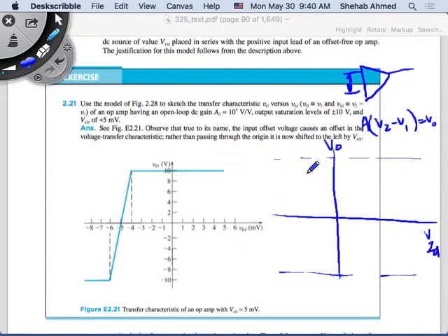And that's why, if the offset voltage exists and you put a short circuit here, you have an offset voltage. So what's going to happen to the op amp output? It will saturate. This is V offset. It will saturate, but you cannot measure it. You don't know what the offset is, right? Because it's finished. The op amp will saturate. There's no way to measure it here. For you to measure it and know what your offset is, you have to construct some circuit around it for which you control the gain. So you can say, okay, now my gain is X. If I take the output now and divide it by X, then I know what my offset voltage is. I can deal with it in that case.